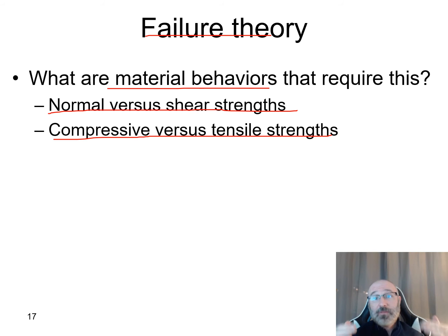Think about a bridge deck, the way it's loading in three-point bending. Sometimes it's in compression, sometimes it's in tension. Go back to some of our previous courses where we talked about that with three-point bending. If you look at a beam in three-point bending, if it's going down like this in the center, all of a sudden the bottom of that beam is going to be in tension and the top of that is going to be in compression. The same applies for a bridge deck, where you're going to have certain portions in compression, certain portions in tension, and it could be cyclic loading as cars are driving over it, going back and forth, putting the top in compression and tension and the bottom in compression and tension as well. So that's interesting to see, comparing the compression versus tension results.